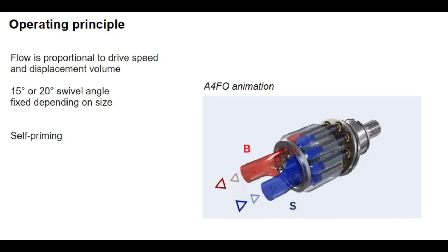By the inclination of the swash plate, each piston moves during one revolution on the top and bottom dead center back to its initial position. This causes the hydraulic fluid corresponding to the displacement to flow through the 2 discharge ports in the control plate. Hydraulic fluid enters the increasing piston chamber on the suction side. At the same time, hydraulic fluid is pumped out of the cylinder chamber by the pistons and into the hydraulic system on the high-pressure side.